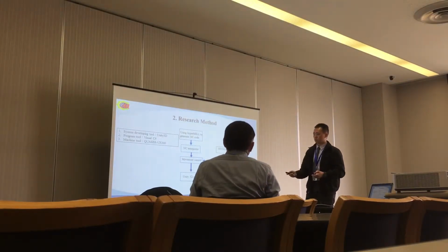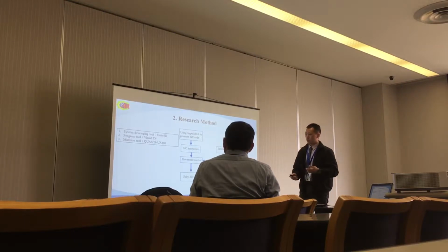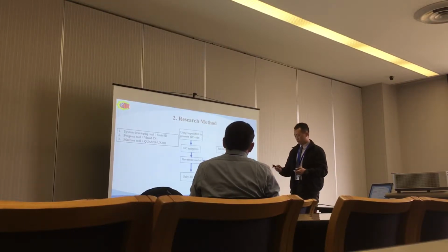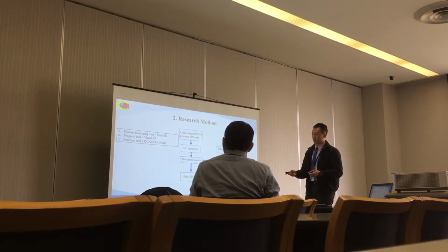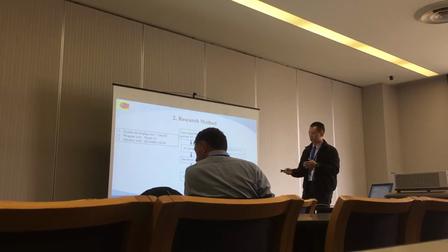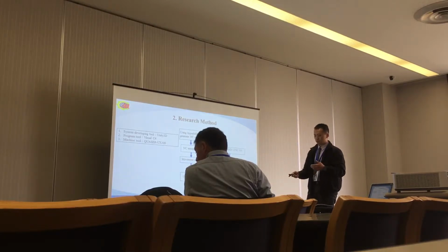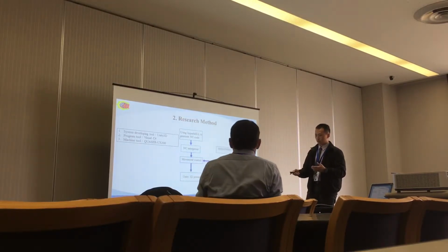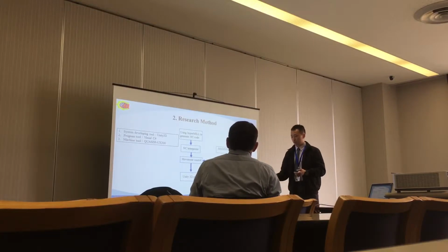So here's our research method. We first obtain the NC code generated from the hyperMILL. Then we use Visual C# to develop an NC interpreter for Heidenhain. And then we convert those NC codes into moving positions. Once we got the moving positions, we can present the 5-axis processing in Unity 3D.